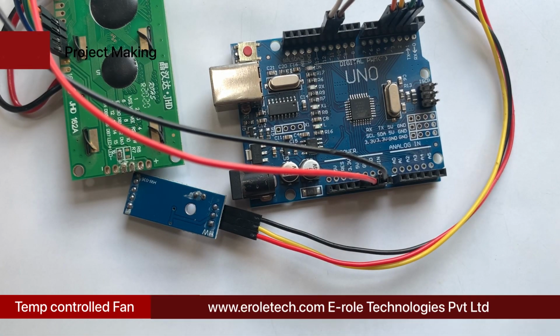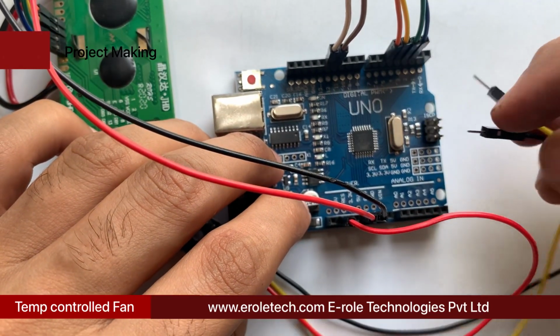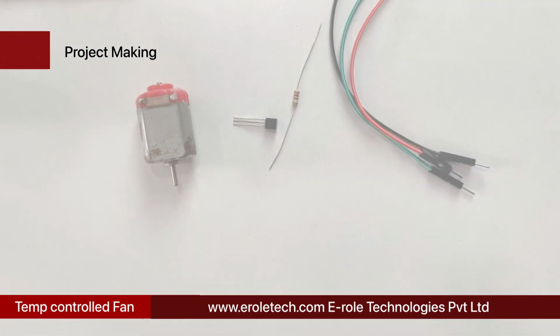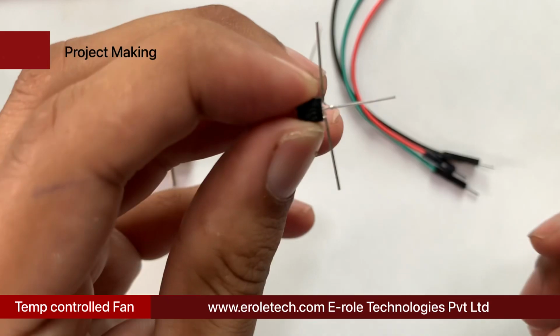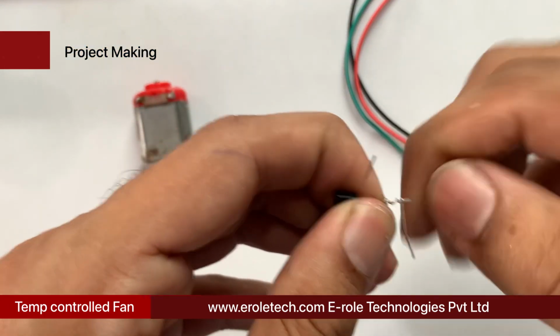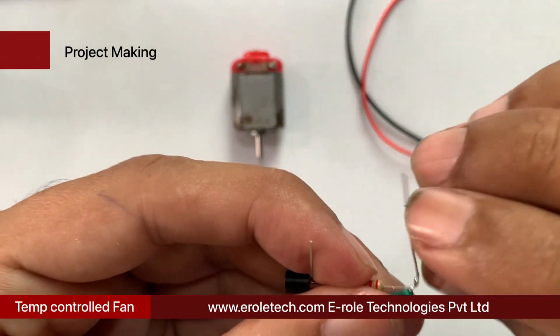Now connect the red wire with the 5 volt pin of Arduino, the black wire at the ground pin, and the yellow wire at the A0 pin of Arduino. Now we will take an NPN transistor BC547. We will connect a 220 ohm resistor at its base terminal. Now we will connect a green wire with the second end of the resistor.